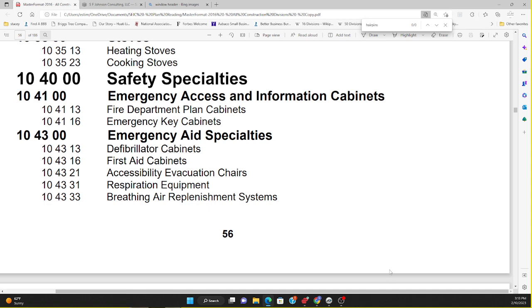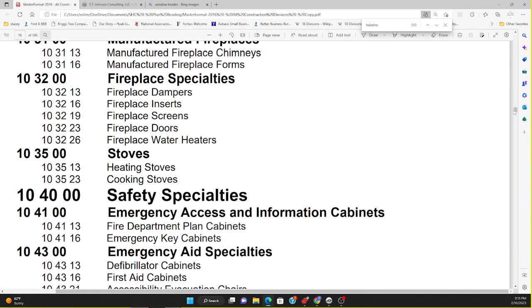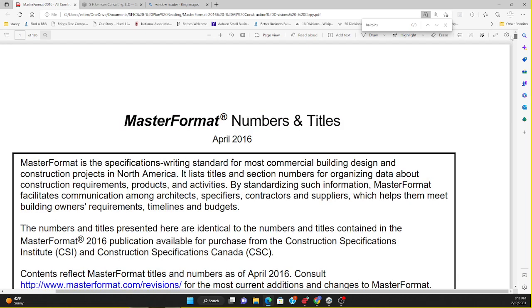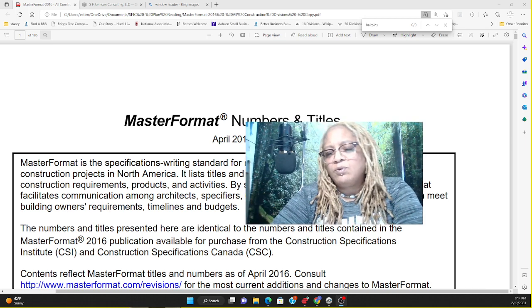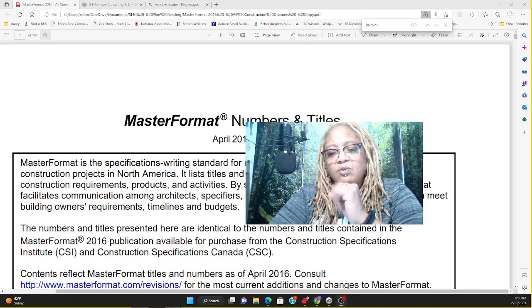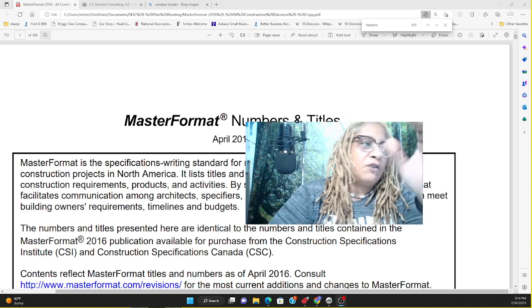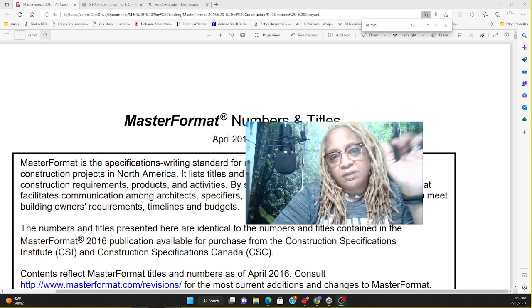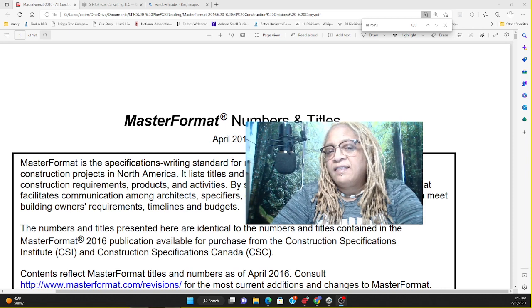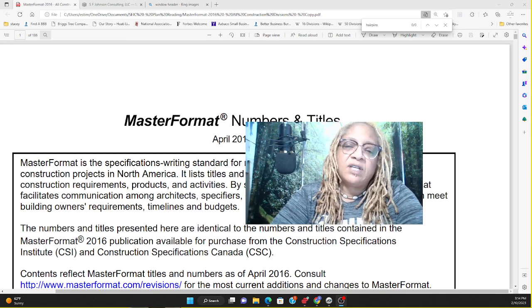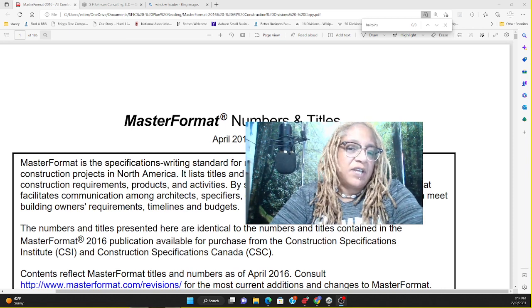That's not in there. All right, so what are the specifications? Written words that go with our project. It's very, very important to make sure that you review that. You review it, you make sure you take notes, and this is always what I recommend. You go through the specifications first, take notes, and then you look at the plans, and you never forget what you read in the specifications.